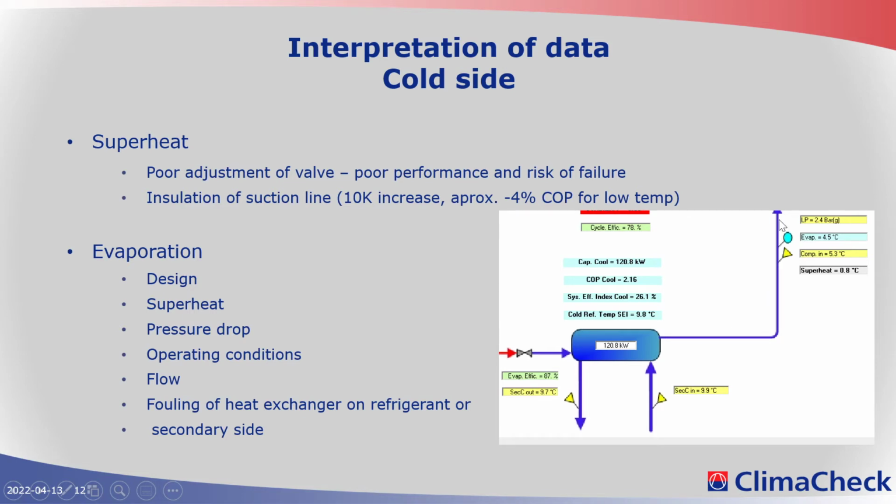So if the suction line is long, it could have significant pressure drops and so on. But if I measure the superheat at the compressor, which I need to evaluate my compressor, then of course I can judge if the additional superheat from the suction line makes sense to what the expansion valve is controlling.